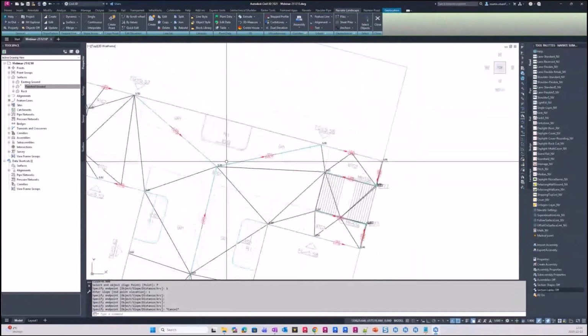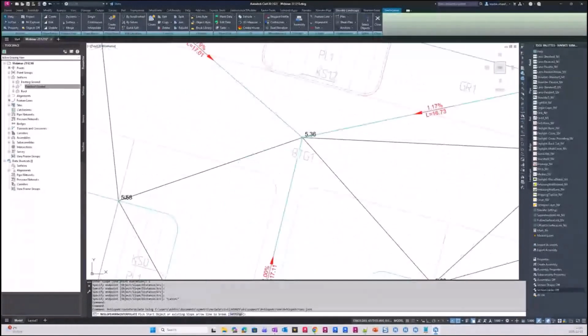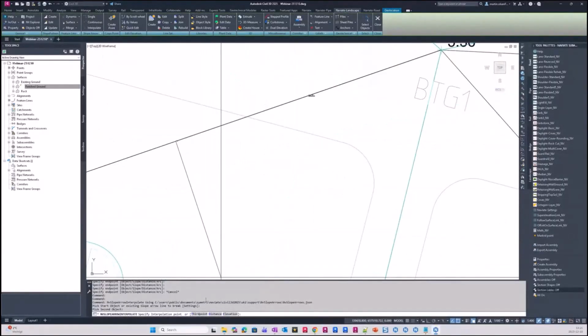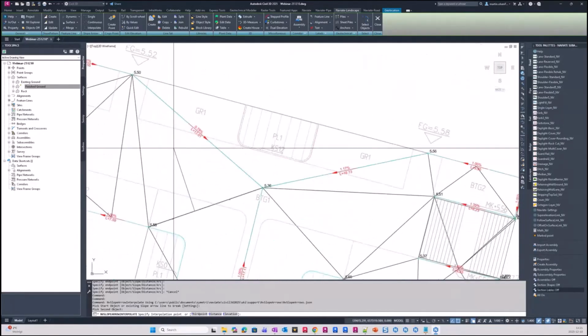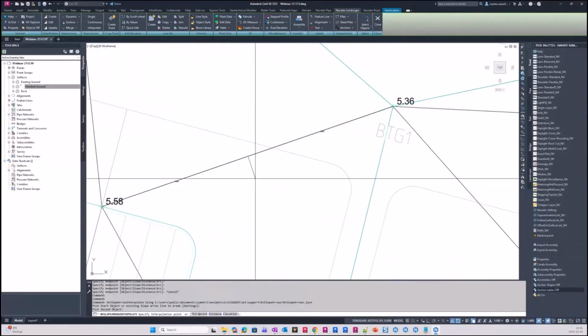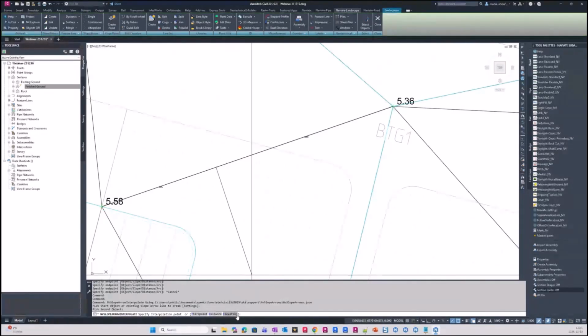And we also got the opportunity to interpolate between 2 or 3 points here. So if I choose this interpolate function, I can just pick my first point I want to interpolate between and the second point. And then I can pick a third point if I want to. It will interpolate between all those 3. Or I can pick a distance from any of these points that I want to create this interpolation between, or I can pick an elevation that I want this point to hit.